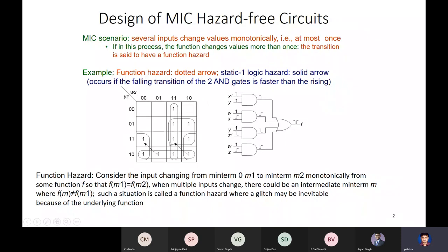So you OR every bit. If you have a minterm, every bit, starting and ending, you OR, and if there are n bits, you have n such product terms, and the resulting expression you get will correspond to the cube, which is the transition cube. And visually it means that it encloses all this. In this case, it's only these 4, but if you consider wraparound and cyclicity for longer transitions, there will be larger cubes.